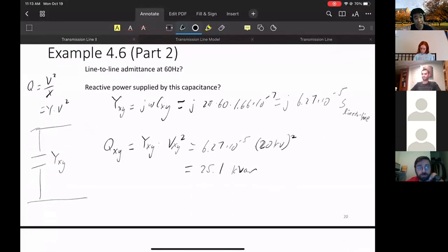When you have transmission lines, they have inductors and capacitors, and they can be modeled by inductors and capacitors. And in practice, what is the impact? The impact is they just consume reactive power. So when you have a generator, your generator needs to generate reactive power.